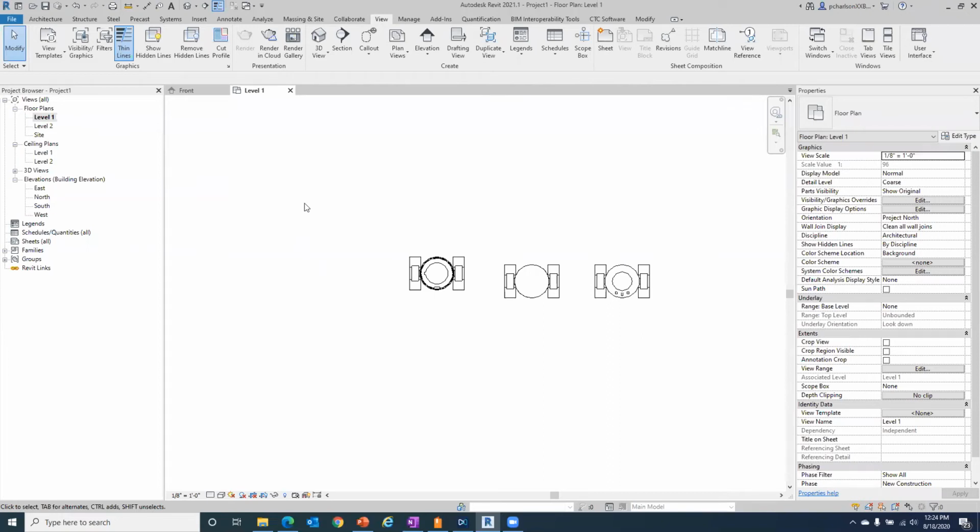So create a dummy project, and typically what I do for content that I'm creating is I create a very small square building, throw some windows, doors, put a ceiling, roof, floor in there, some interior section cuts, interior elevations, so that you can just pop in a family and go to all those different views that you have set up.